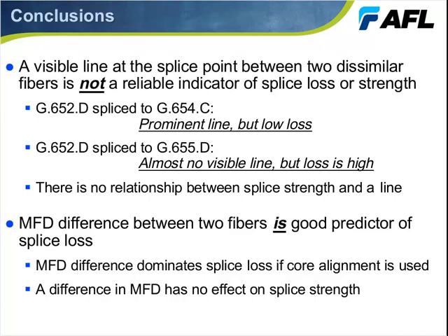Well, I think if we're talking about fusion splicing, there are many things that come into that. I would say, first of all, in terms of increased attenuation, unless something rather dramatic happens, a fusion splice typically has very good integrity and doesn't really change due to atmospheric or temperature conditions unless there is somehow some dramatic stress on it that causes it to break or something like that.